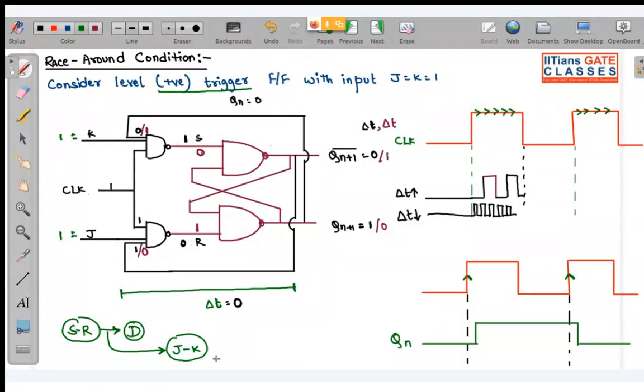So when we connect output to input, what is that process known as? Feedback. Very good. So the previous thing which was acting as a boon is now becoming a bane. Now that feedback is actually causing this continuous multiple transition.